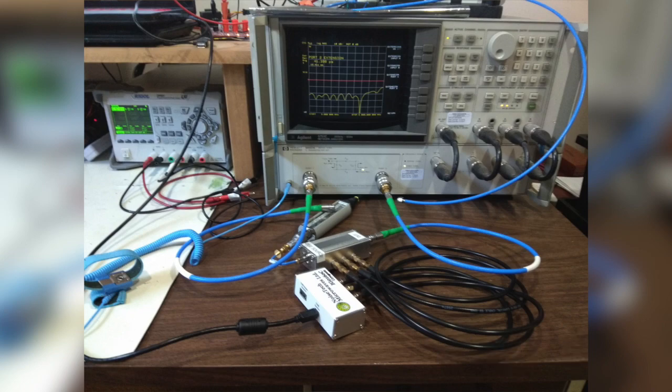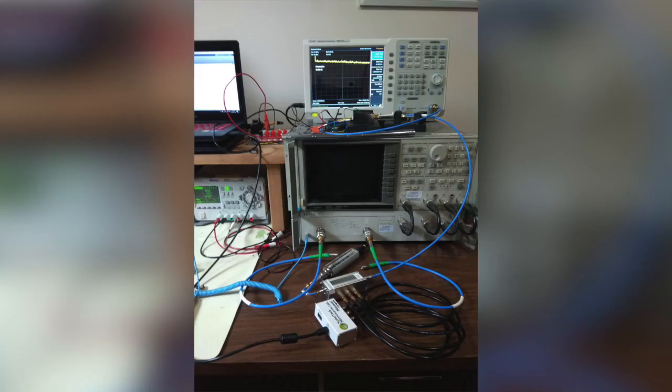And that's everything for steps 5 and 6. So the next two steps, steps 7 and 8, we now connect the receiver or the spectrum analyzer with the preamps to the DUT connector of the impedance generator with the noise source also connected. At this point, we're done with reflection coefficient measurements, so you can power the VNA down.